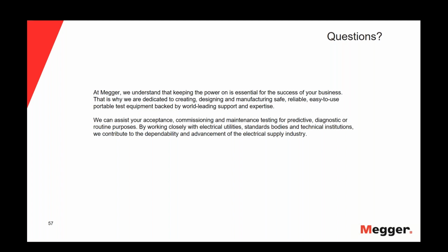Besides the Tan Delta test, what other tests are available to detect aging conditions? Well, probably today, the most utilized test to detect aging conditions is a Tan Delta test, because it measures the change in dielectric properties of an insulation material, which can be caused by water tree aging is one of them, but it could also be thermal aging, for instance.